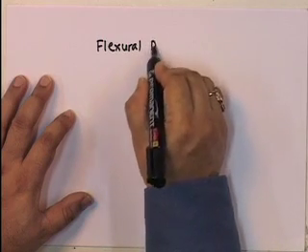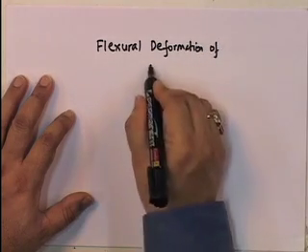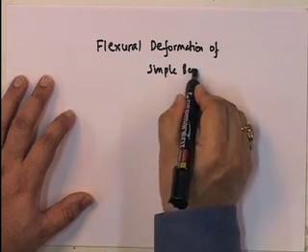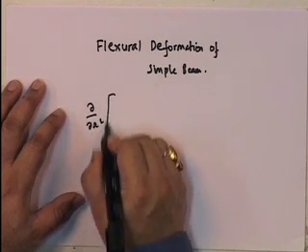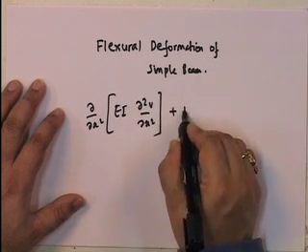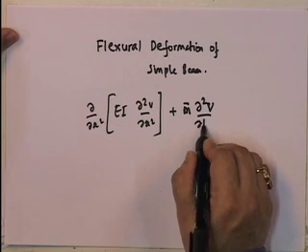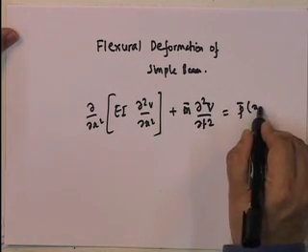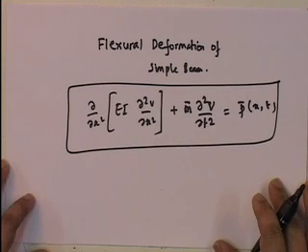But before I go into those, let me look at a particular problem that I had talked about, and that is, remember the case where we only looked at flexural deformations of a simple beam, and we got the equation d squared upon dx squared of EI del squared v by del x squared plus m bar d squared v by dt squared is equal to p bar x of t. This was the equation that we wrote down for a flexural beam.